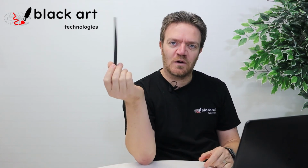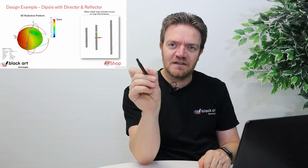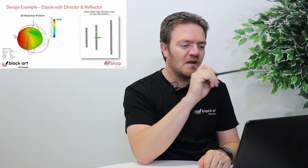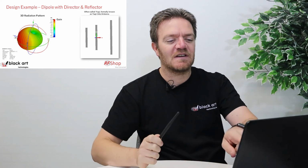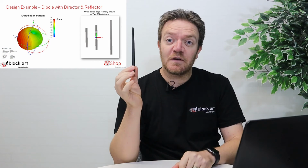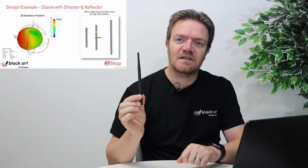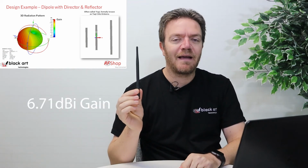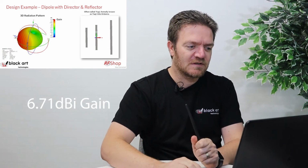Now, take it further, and I actually convert this omni into what we would call a classic Yagi or Yagi-Uda antenna, which is patented in 1926, but I mentioned that in the other video as well. Now you actually take this further, and you can go on further and further to add more directors to the actual antenna itself. But in this case, you now have the reflector at the back, and you add a director to the front. You still have the original same dipole, so I didn't change the basic thing that I have. But see, now the gain has increased to 6.71 dB, gain in one direction. It's taking it from the back, so we are moving all the gain in one specific direction.